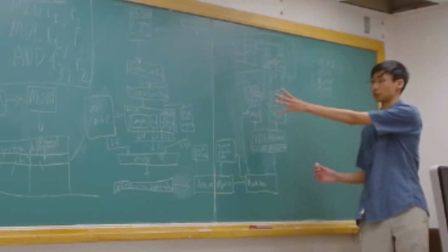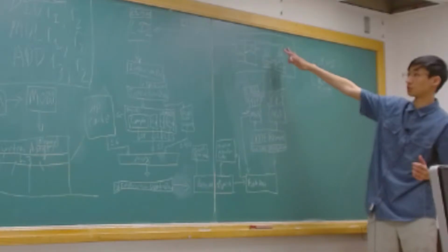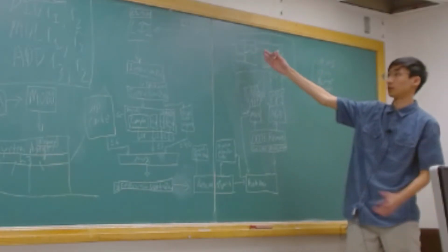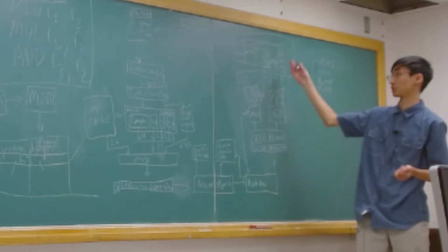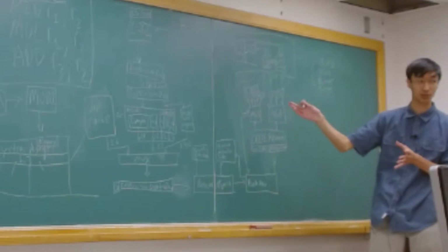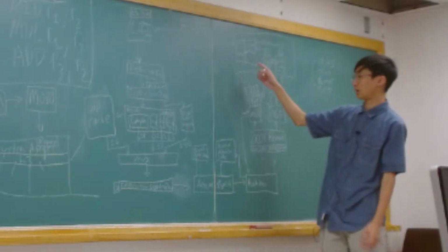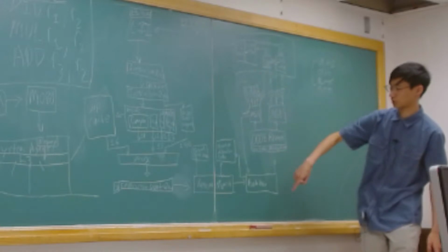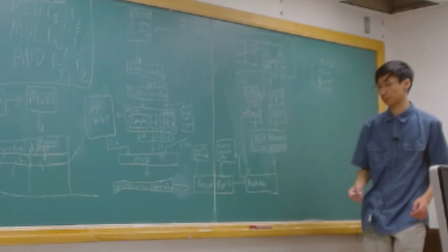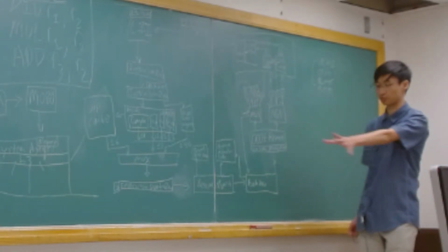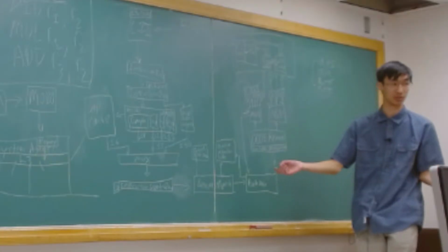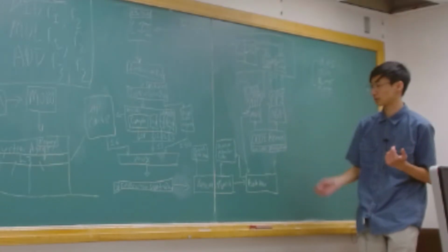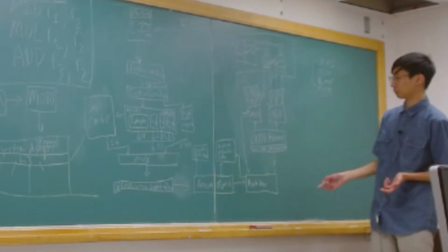We'll execute operations. We will do loads and stores. We'll push them into our cache or pull them out of our cache, make sure that the dependencies are managed, and then we'll also retire our instructions. So once the instructions are complete, we'll tell the reorder buffer and the rest of our out of order system, hey, we're done with this instruction, and now we're out. Now, that's a lot of work to do.